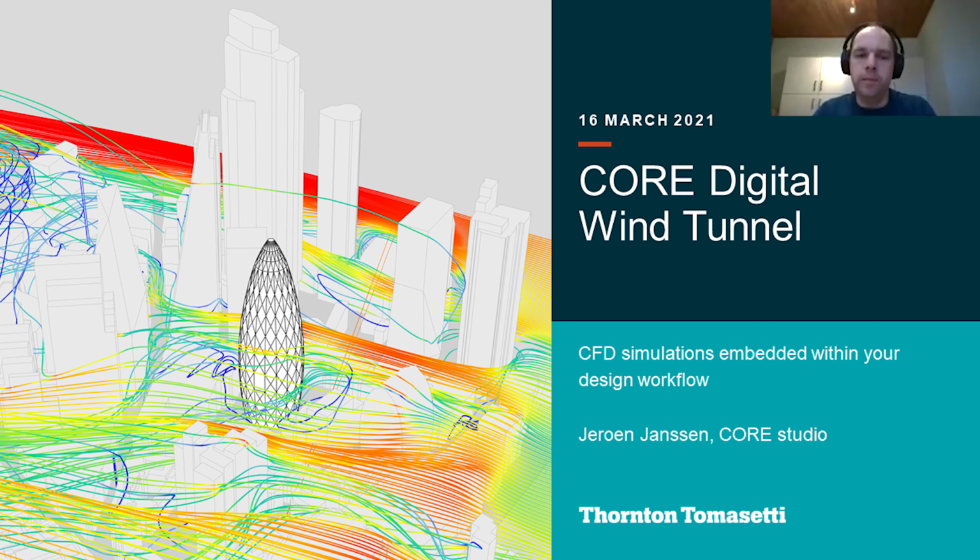And you then measure the pressures on all the facade, and you integrate that to find the results. By deflecting, the building actually changes the wind pattern and vice versa. So they interact. In CFD simulations, you can do that as well. They're called fluid structure interactions. They're a lot more complex to set up. A lot of technical things like the meshing needs to be correct, etc.